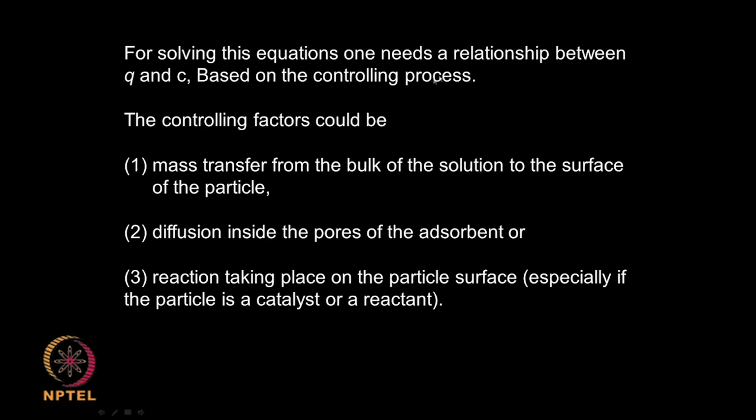For solving this equation, one needs a relationship between Q and C. So, between Q and C, you can have a linear adsorption, you can have non-linear, a Freundlich, Langmuir and so on. Then you also have to have controlling factors, if there is a mass transfer from the bulk of the solution to the surface of the particle, because the solute has to move from the bulk of the solution, come to the surface of the stationary phase and get adsorbed. Then there could be a diffusion inside the pores of the adsorbent, if the pores are very porous.